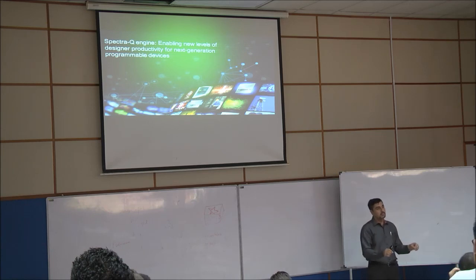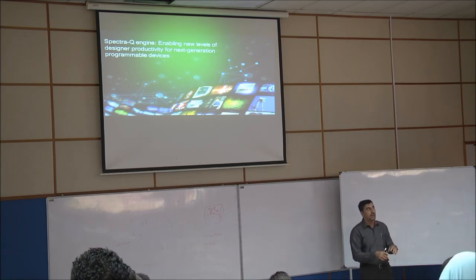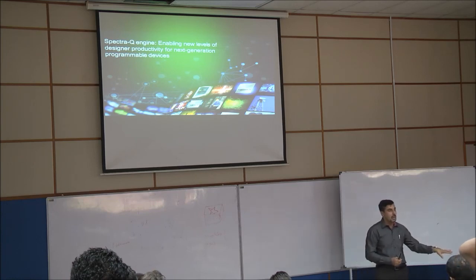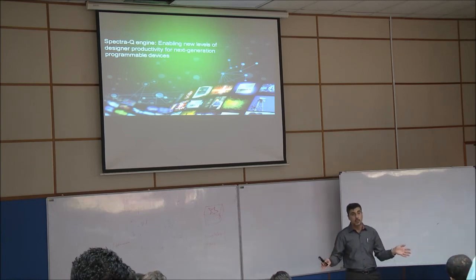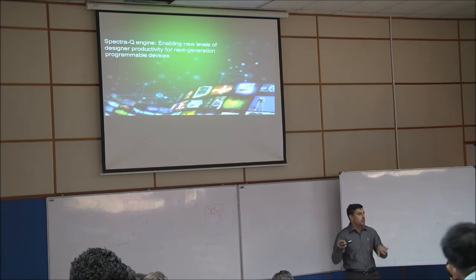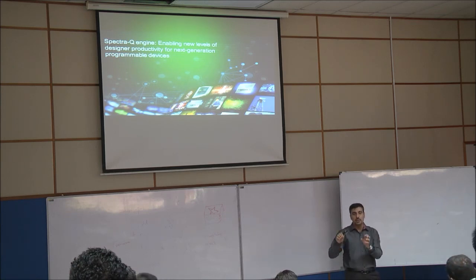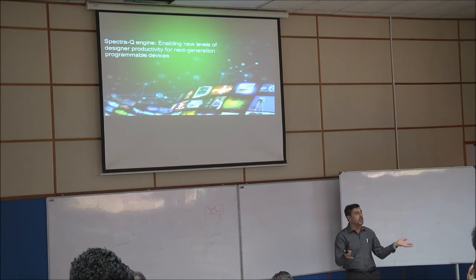Why am I saying this? To design on FPGA, you have to know, for example, that I'm designing with the DE2 board. The DE2 board has a Cyclone II. If I'm designing using the DE1-SoC, it has a Cyclone V SoC. So different chips, both FPGAs but different chips. What is inside the Cyclone V that differs from the Cyclone II? There is something common, yes: both have logic elements, right? But the memory side is different. The architecture itself is different.